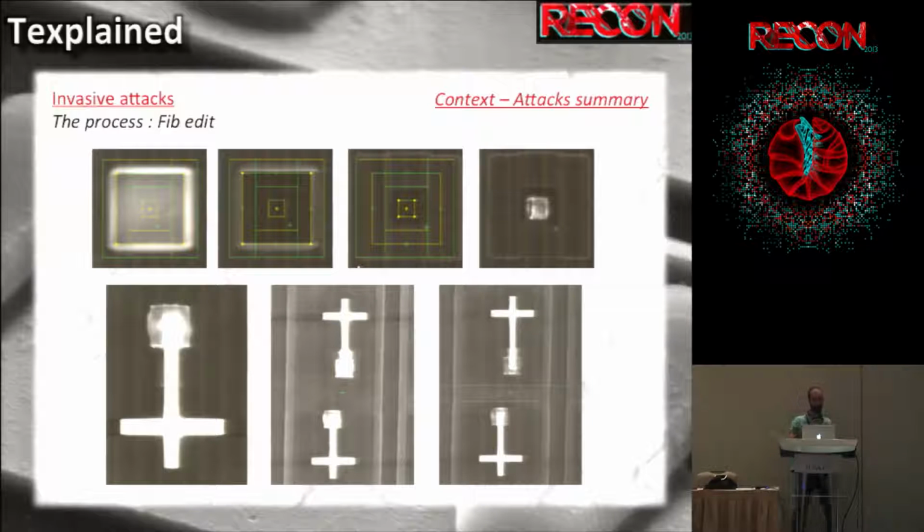So I put some oxide, and then next picture, I just continue to etch my chip until I see the line I want to connect to. As soon as I see it, I just have to put some tungsten and make a pad. So after, I can create another connection and isolate them properly to make sure everything is fine. So that's the basic process.